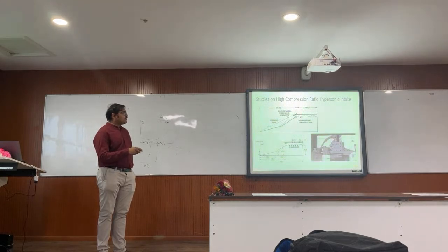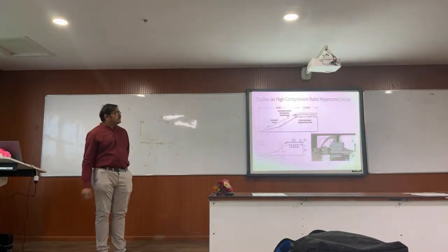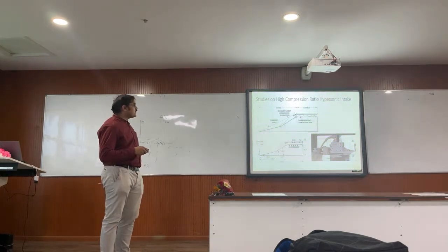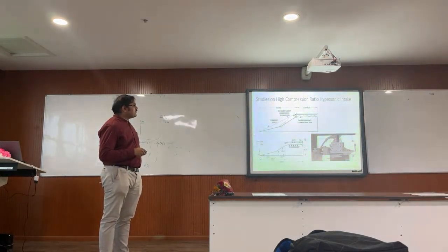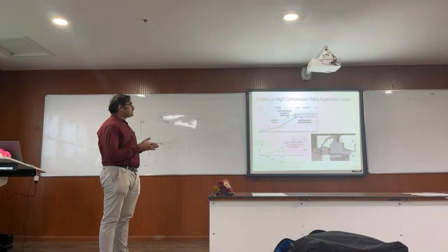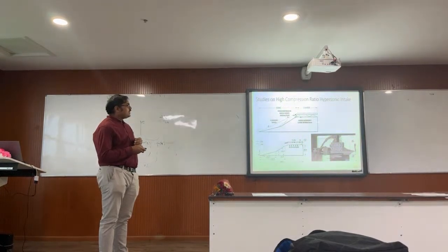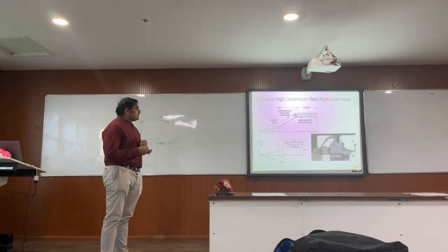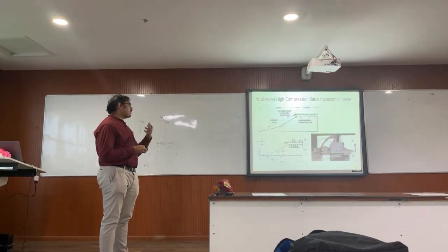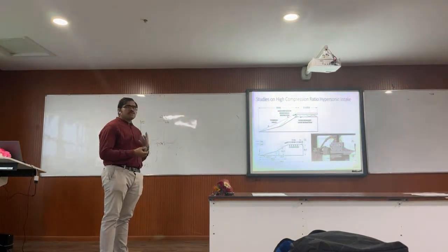So you can see this is the intake. This is called the mixed compression intake, because in this there is a set of shock systems which are away from the internal duct. This is the internal duct. Then this is called the isolator, which is a duct which separates the intake and the combustor, and it holds any shocks that are produced due to some changes in the back pressure at the combustor side. In our experiments, we produce changes to the back pressure by means of a flap or a throttling kind of system.